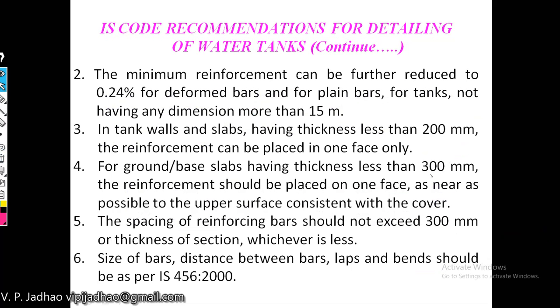Then the second recommendation for detailing is that the minimum reinforcement can further be reduced to 0.24% for deformed bars, and for plain bars, for tanks not having any dimension more than 15 meter.